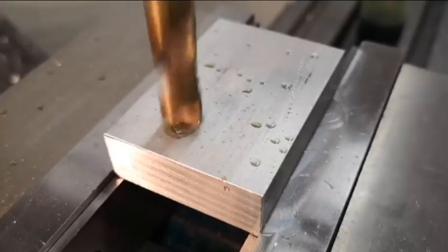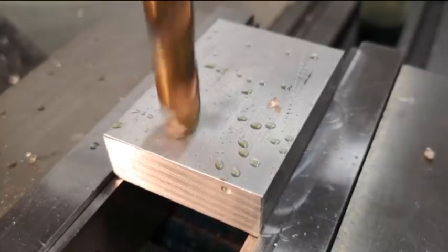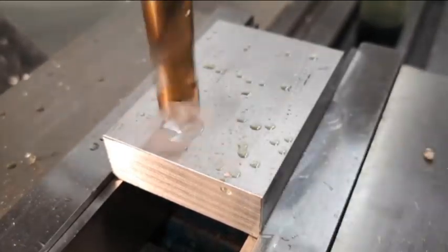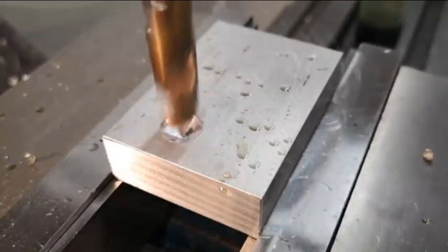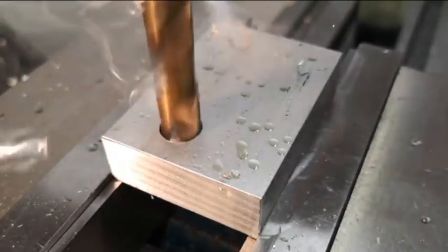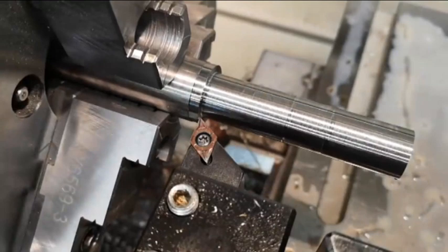Likewise, if you have to design something to fit inside a drilled hole, even if you don't have the tolerance for the hole in front of you, you can look up drilling and see that it has at best about IT10. So the whole basis for the fit is going to be around H10. So why would you use this system?